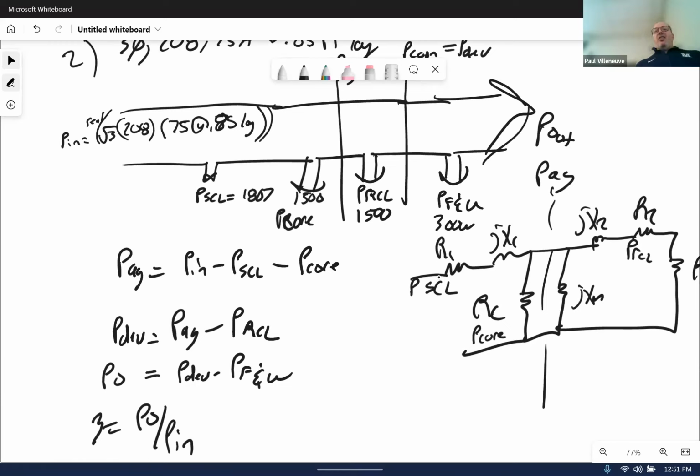But once we start getting into mechanical losses, this is the world where our mechanical engineering friends can actually talk with us, right? Because if you tell them, hey, I've got this input power, it's 50 kilowatts, and then I'm dropping this power, this power, this power, mechanical engineers understand power losses really well. But once you start drawing the circuit analysis part, they might not see where the rotor copper losses are. They don't need that when you put in this diagram with the different locations. What is air gap power? What is converted power? What is output power? That hopefully makes a little more sense.